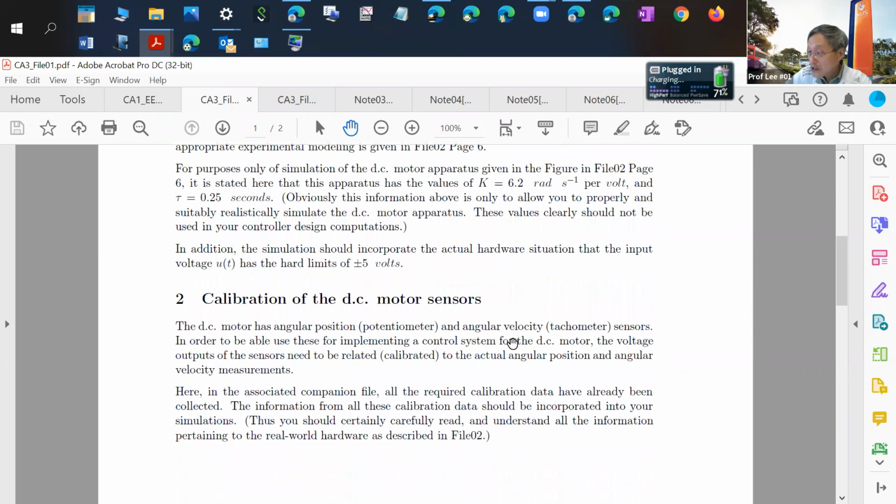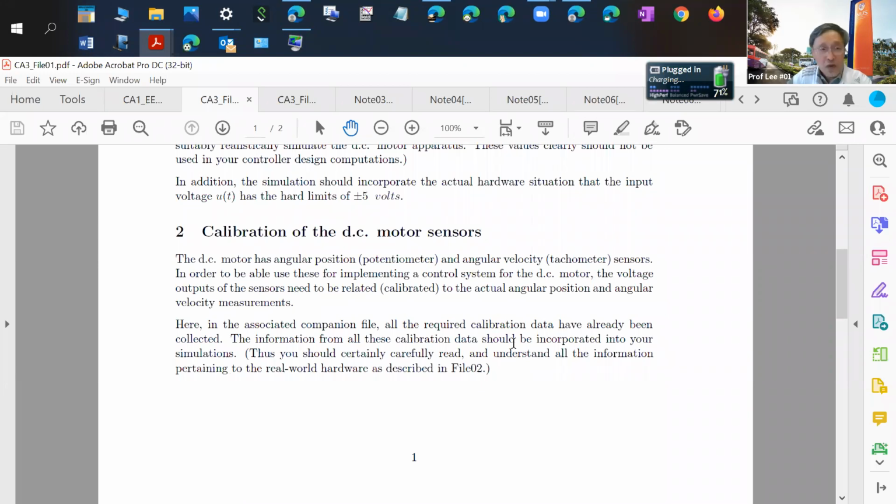Then also, I want to make it very, very realistic, because no matter what kind of fancy control you are using, some of the motors can be put such that they're not evenly loaded. Because in the robotic arm, it will not be evenly loaded and it will depend on the position of the loading. So in my early days, I had even put together radial basis function neural networks and done an equivalent of a non-linear adaptive controller for that.